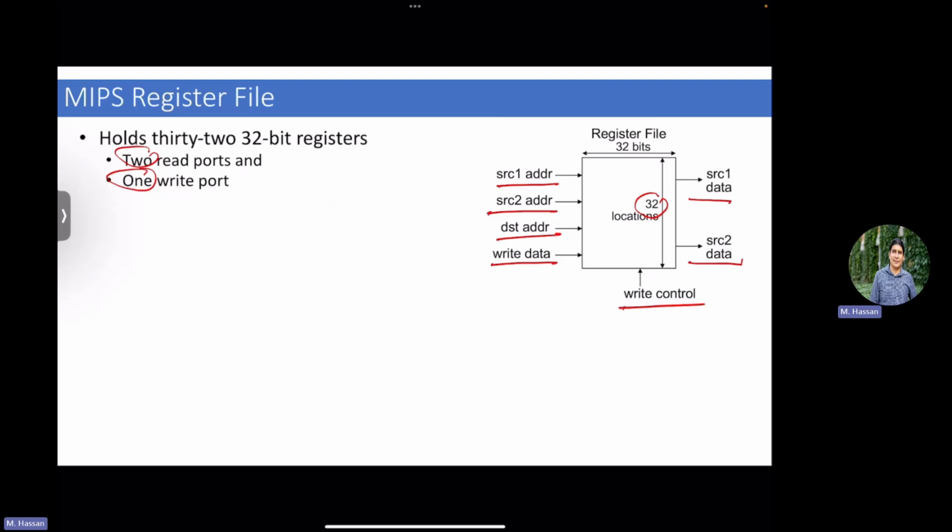But the point of faster is not completely true, because a port has a high cost that is known. Like anyone that is working, for example, if you had a co-op at a digital design company or somebody that goes through silicon manufacturing, ports are the most expensive resource in terms of area, right? You want to minimize the number of ports at any expense. Good. So having a higher number of ports means definitely higher area. Why is area problematic? It's higher cost. You take more area in your chip, you have to pay more. Good.